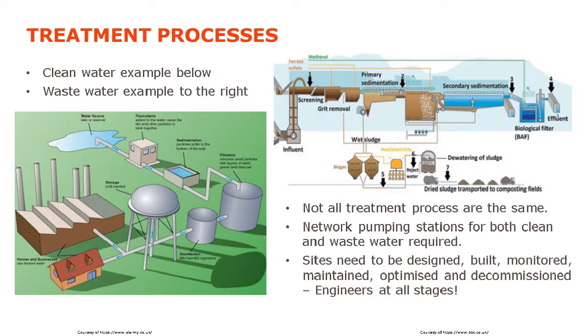Over on the right is just another typical example. Not every wastewater treatment works is the same; it's very unique for every wastewater treatment works. It all depends on what foul flow is coming into the works and how it's to be processed. This particular example uses preliminary treatment of screenings and some grit removal.